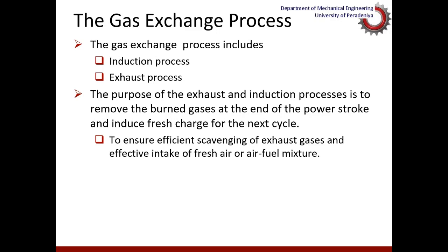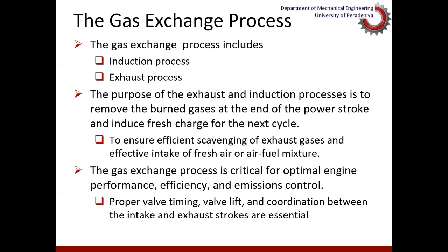Even though the power is produced during the combustion process or the expansion stroke of the engine, the intake and exhaust processes are also very much important for the performance of an engine, particularly parameters like valve timing, valve lift, and proper coordination between intake and exhaust strokes.